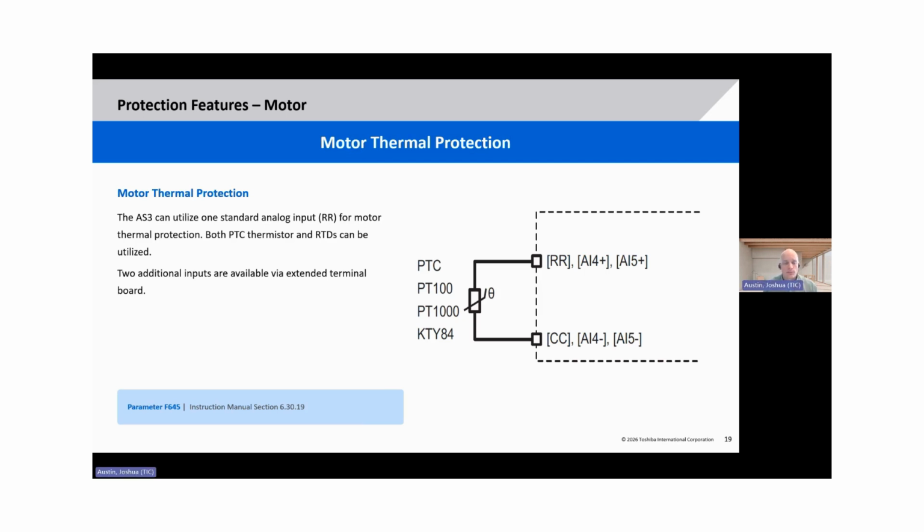When it comes to motor thermal protection, the drive doesn't have any type of thermal sensor built into the drive. That sensor has to be embedded inside the motor itself, whether that's PTC, positive thermal coefficient, or RTD, resistive temperature detector, so that those devices can actually be wired in from the motor to the drive itself, or you can use separate motor protection relays if you want.